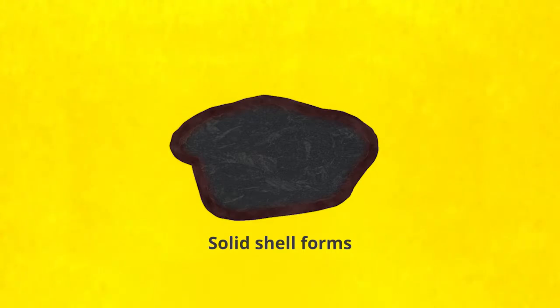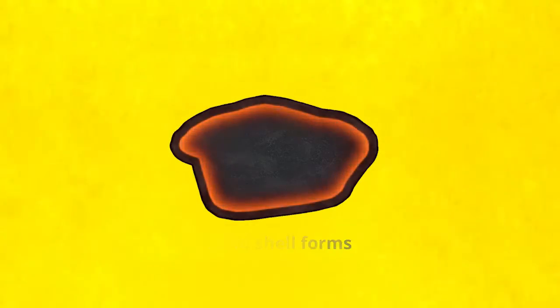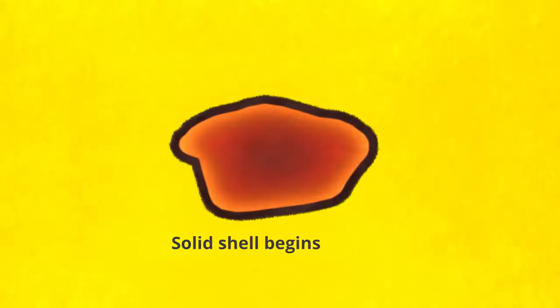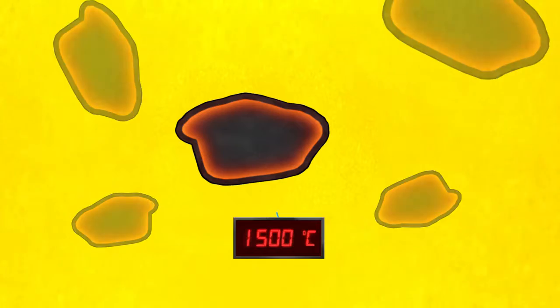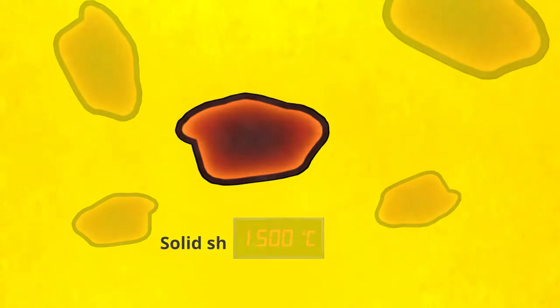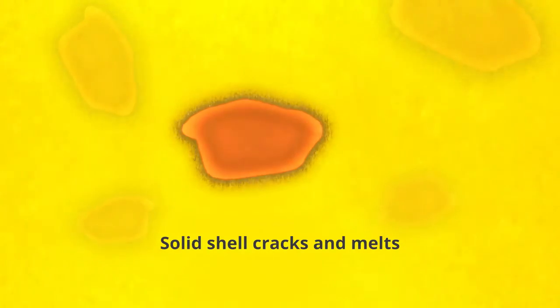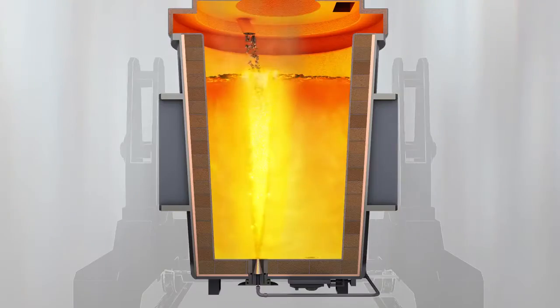This shell gradually thickens until the temperature equals that of the steel's liquidus temperature, at which point the shell begins to remelt. However, in the meantime, the core of the ferroniobium particles will have reached a temperature above 1500 degrees centigrade, and it interacts with the steel from the shell and starts to melt. The shell and core continue to melt, and the process is accelerated by vigorous stirring and careful control of temperature. The process repeats itself as the unreacted core material is uncovered.